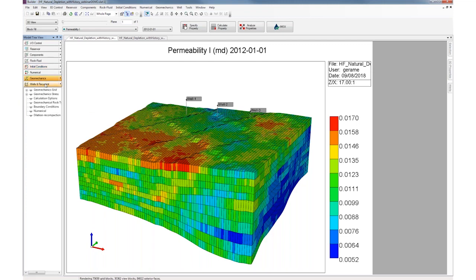There is an additional geomechanics option that's available in all of our simulators, IMEX, GEM and STARS. We do offer high fidelity geomechanics modeling, which implements finite element analysis in your grid that simulates stress and strain in your reservoir rock. This high fidelity advanced geomechanics modeling can also be used to identify any splitting of grid nodes, such as in the cases of fracture initiation and propagation of hydraulic fractures. We also offer low fidelity geomechanics modeling, such as simply using dilation and compaction tables to characterize the porosity and permeability of your rock according to specific pressure changes.